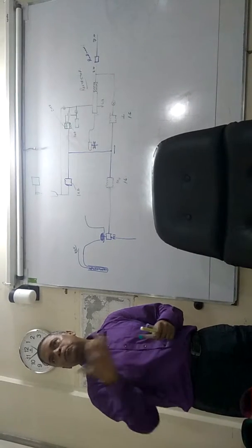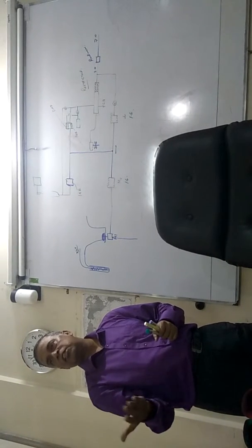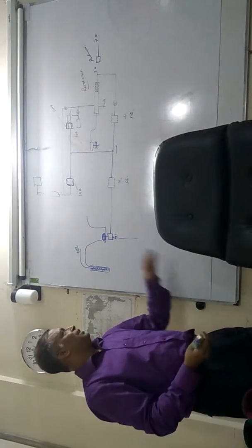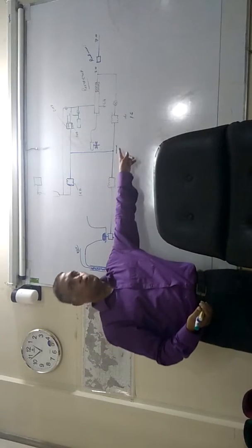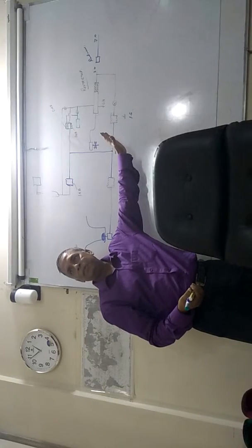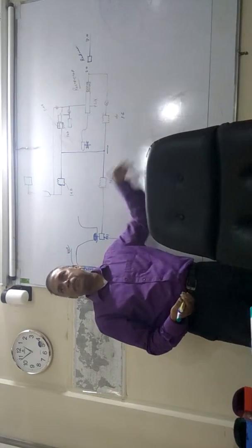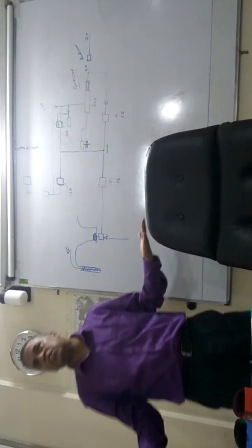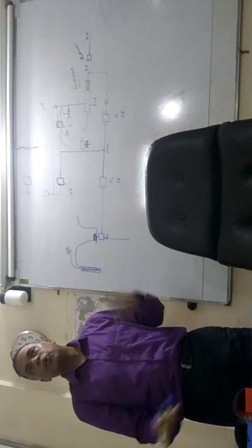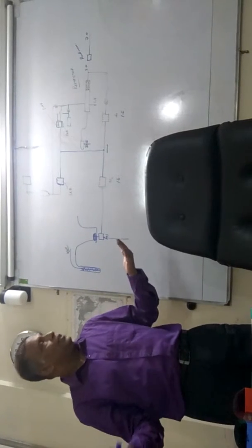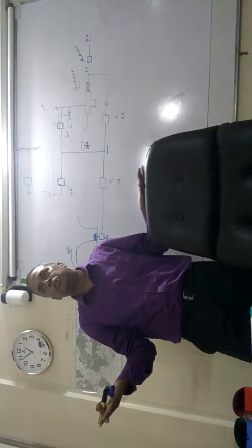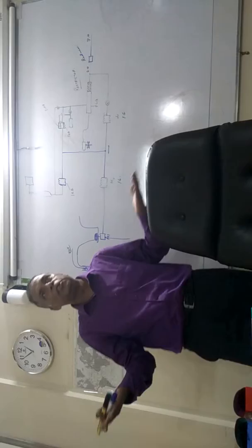Bottom of the flapper will move to the right for a certain rise in temperature. And you can also understand, if the temperature is 81, it goes some distance; for 82, the pressure here will increase a bit more, so it will go further right; for 83 even more to the right, for 84 even more. So it is a proportional signal, proportional motion of the link towards right. For a receding temperature, it will move to the left, and similarly in proportion. So no problem with that, right?